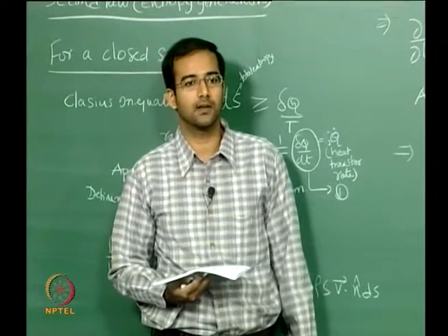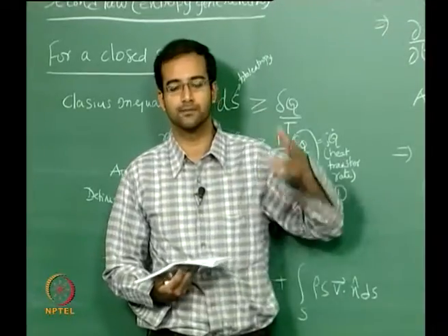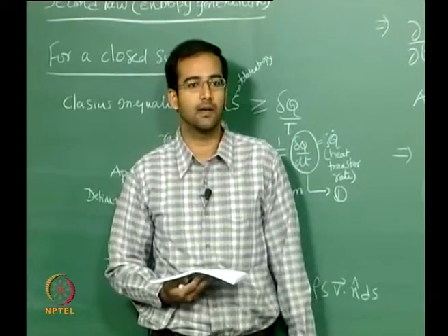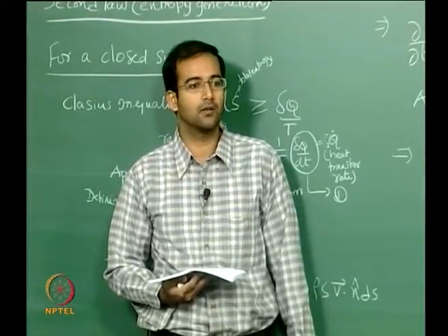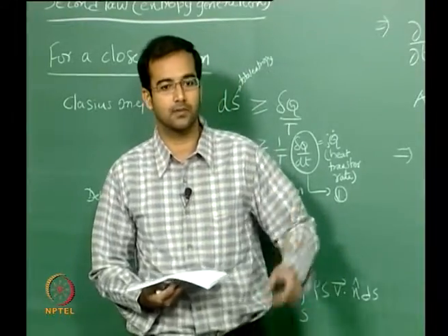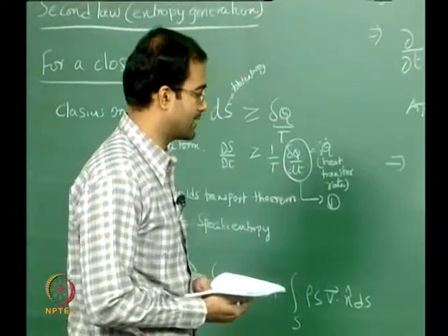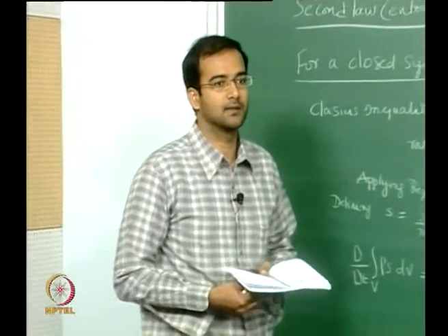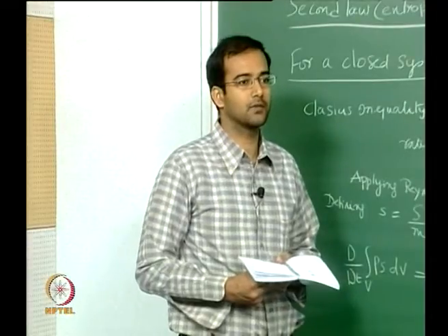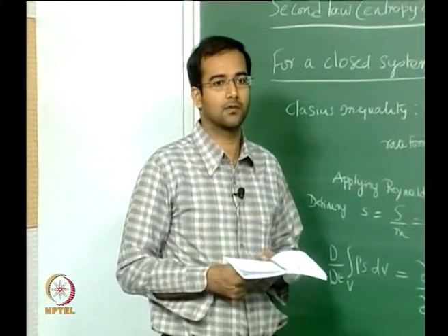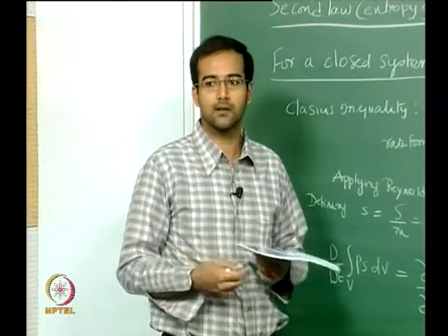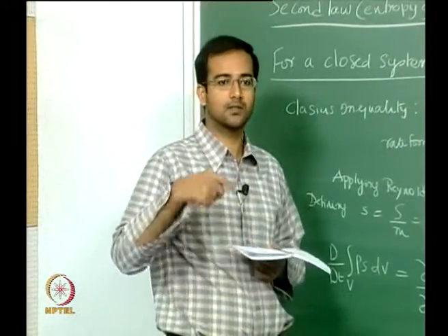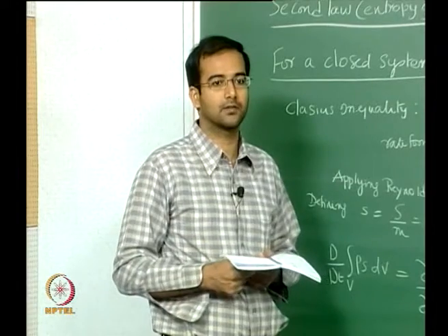So numerically there are some techniques to overcome this hurdle, where we construct an artificial pressure equation and things like that. If you want to overcome that, we can rewrite the Navier-Stokes equation into what is called a stream function vorticity formulation. That is very useful when you are looking at 2D incompressible flows. There you have only 2 variables, 2 equations. You can solve that straight away, and the solution is also slightly simpler than solving the Navier-Stokes.